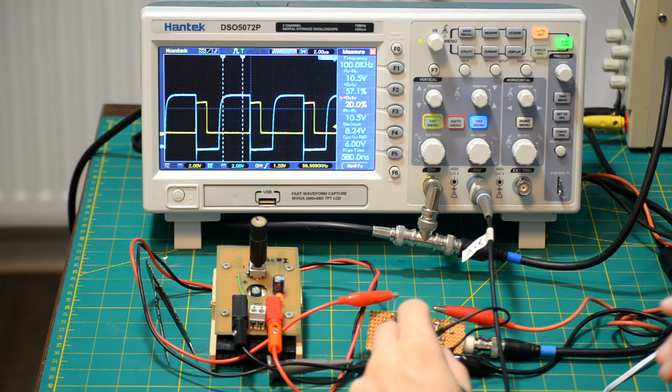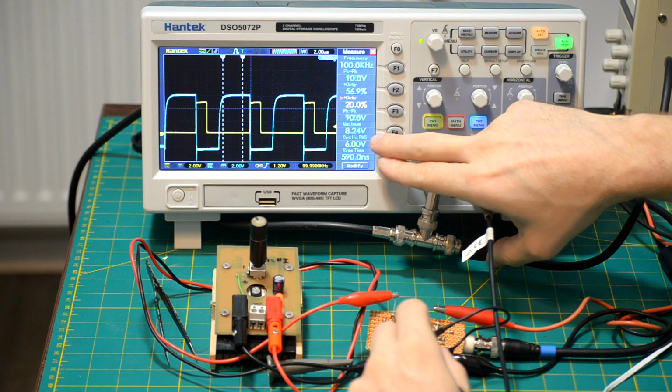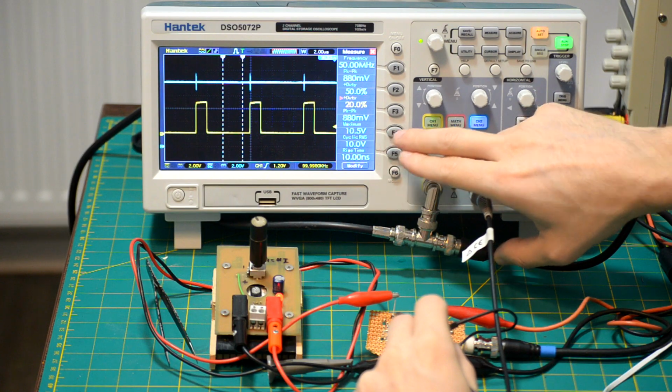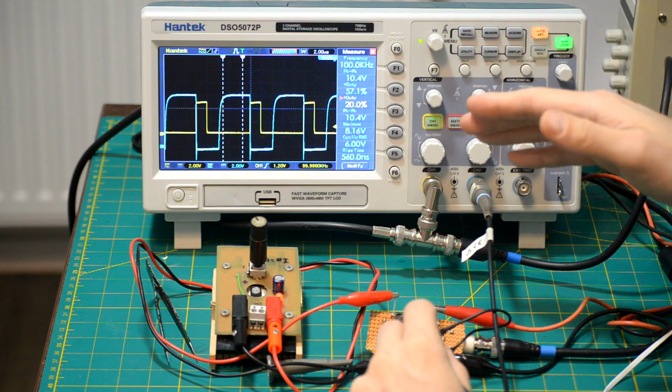So there's one more thing you might notice, and that is that the high voltage in the switching node is around 8.2 volts, whereas the supply voltage, I have it at around 10. So we've lost 1.8 volts somewhere along the way. And that's not a very good thing. I mean, 1.8 volts is a large loss, and it's completely unacceptable. I mean, the slope we can fix with the push-pull driver, but not this.